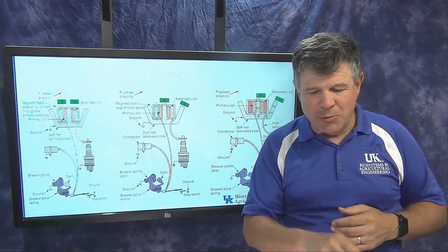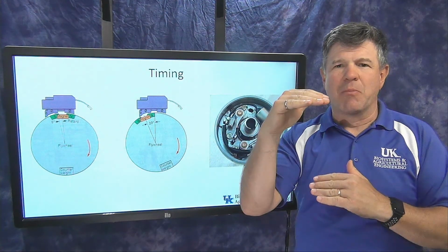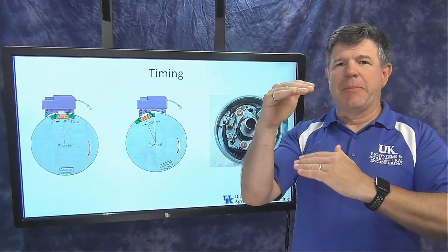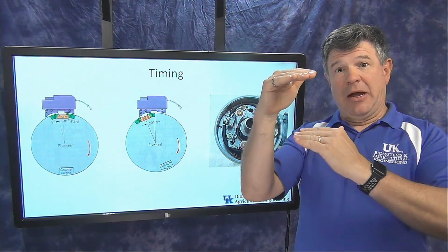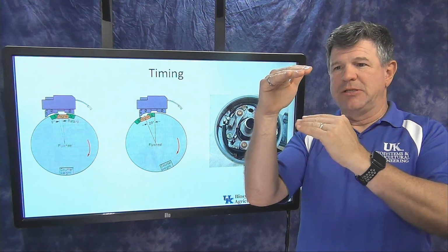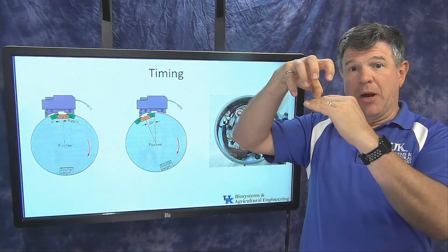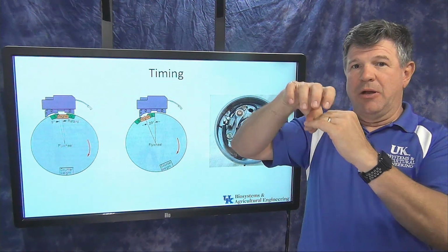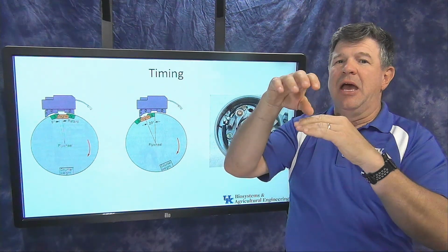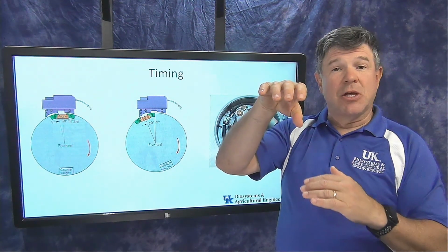Now, I mentioned one more thing about the timing on this. So again, it's really critical, and we will come back and talk more about timing. We'll go into more detail on that and the whole engine cycle. But when this spark happens is very critical. So we talked about, hey, if that piston is coming up and I light that fuel, we're compressing that fuel in that piston, and I light that fuel before that piston gets clear to the top, that's going to start to burn. I'm going to build up pressure, and it's going to be pushing down on the piston while it still has not gotten to the top of its stroke yet to come back down. And so I don't want that spark to happen too early. Likewise, I don't want it to happen too late.